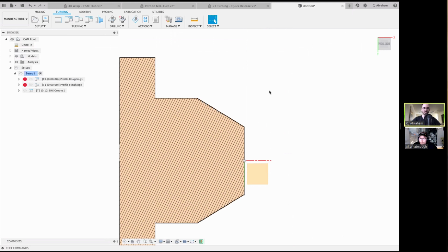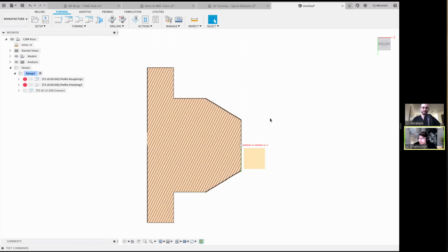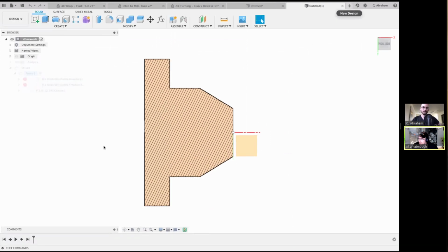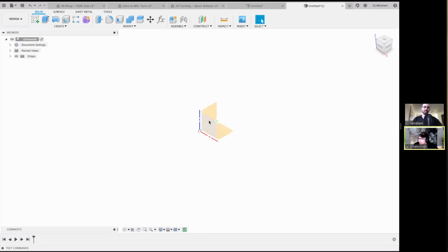Yeah, and speaking about intent, I want to make sure that I understood the intent of the question correctly, because the viewer said face grooving. Yeah, so I was about to tell you that you're covering some good stuff, so I let you. But honestly, you did a radial groove, and I believe we wanted to see a face groove on that. Do they mean that they want the grooving tool turned 90 degrees so that they're axially grooving on the part? I would imagine you've got an O-ring. Let's pretend you've got a large O-ring on that vertical face that's cut in.